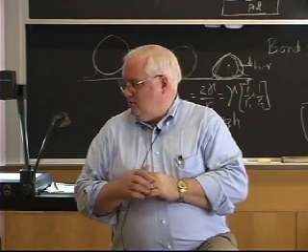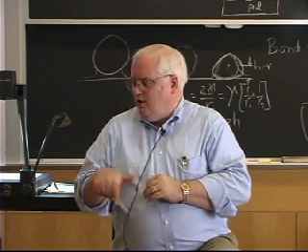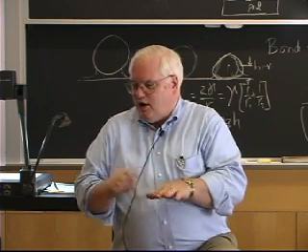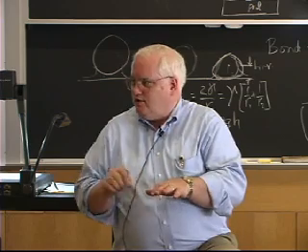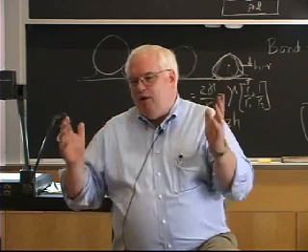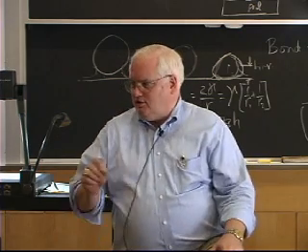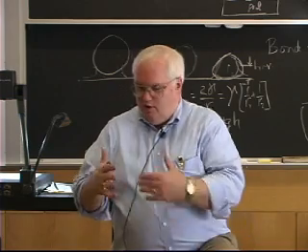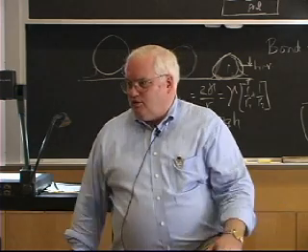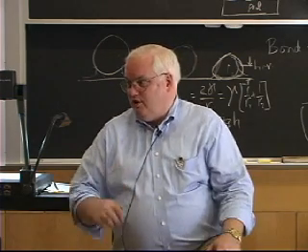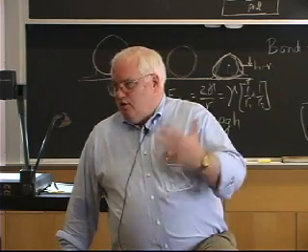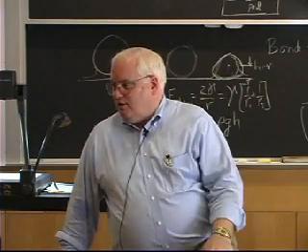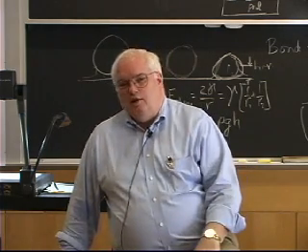So I went down, I was upstairs then, went down to the welding lab, and did the same thing. I just took a gas tungsten arc and melted it, and they all balled up. I only got about 50% yield because the gas tungsten arc kind of blew the balls around, and some of them would join together and get too big. It didn't matter. You could do everything in about 2 minutes rather than 2 hours. So I turned it over to a graduate student to make 10,000 balls and gave the guy his balls.